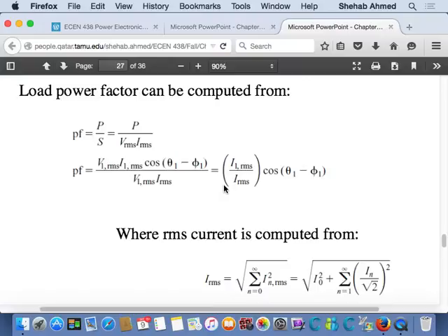So depending on the level of voltage, they will give you margins for the amount of distortion you can add in the system and power factor, right? So anytime you have harmonics in the system, it's clearly reducing your power factor. If it reduces your power factor, it means what? The utility charges you. Okay, it doesn't charge many people here because the employer is paying for the electricity.